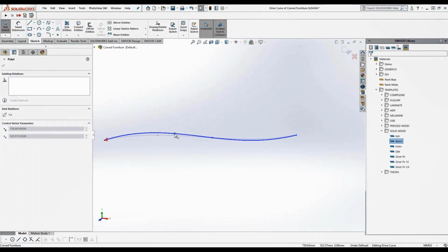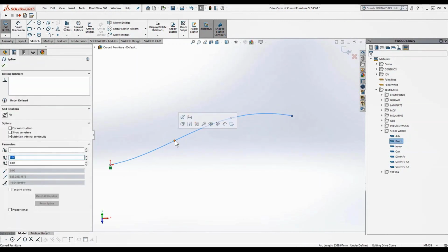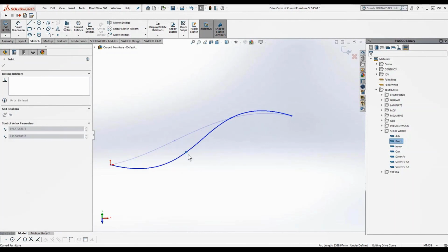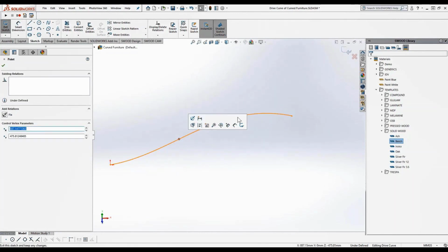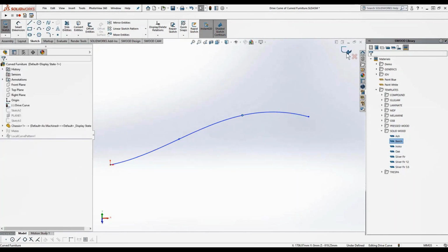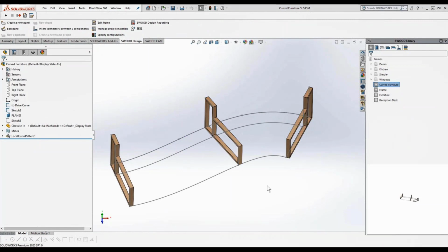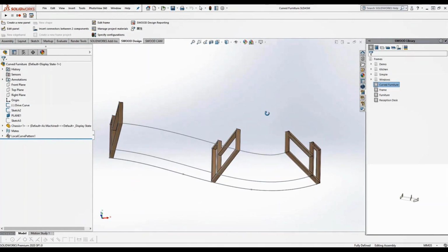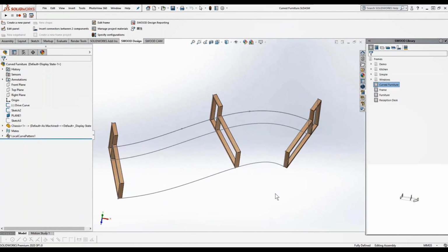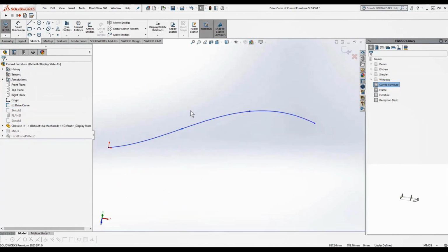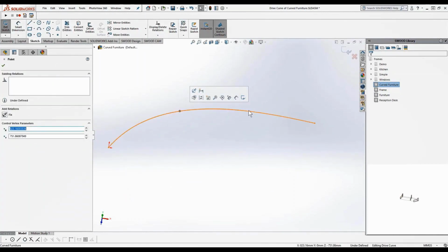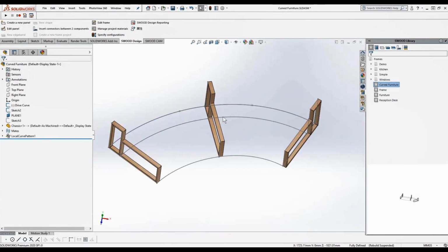Because everything is created by the driven curve, and here we want to modify the driven curve, give him a different position. You can see because all the elements are created by this driven curve, when you change the original driven curve, all the global shape will be changed. So here, the idea is you just need to modify the basic driven curve, and the calculation will be done. Now the work is done.